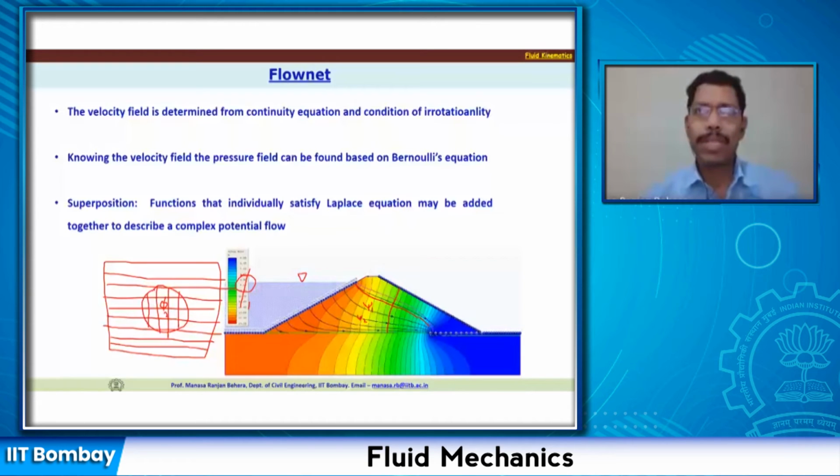So whatever discharge is coming through this is going to also pass through this. And we have also seen another property, there cannot be any cross flow across the streamlines. So the discharge that is coming through this is passing here. So if the discharge is same, we know that this is a larger area or width and this is a lesser width. So same discharge passing through a lesser width will result in higher velocity.